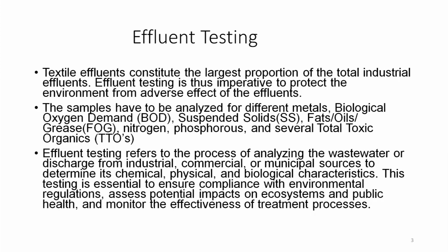The samples have to be analyzed for different metals, biological oxygen demand, that is BOD, suspended solid, that is SS, fats and oils and grease, which is abbreviated as FOG, nitrogen, phosphorus and several total toxic organics, which is TTOs.